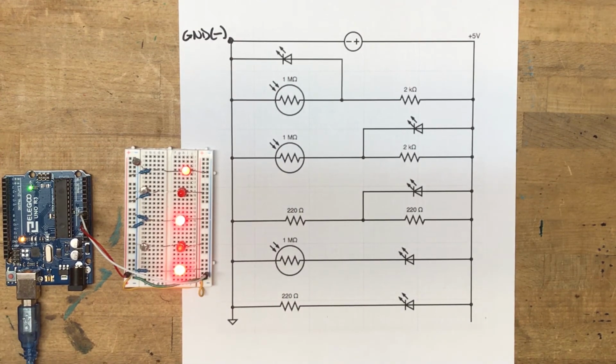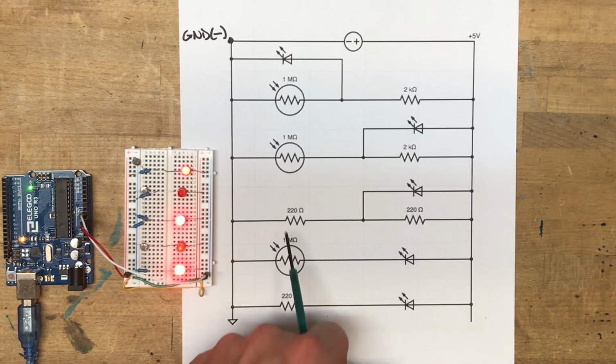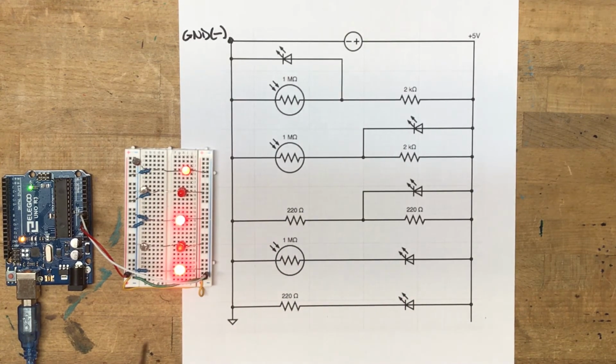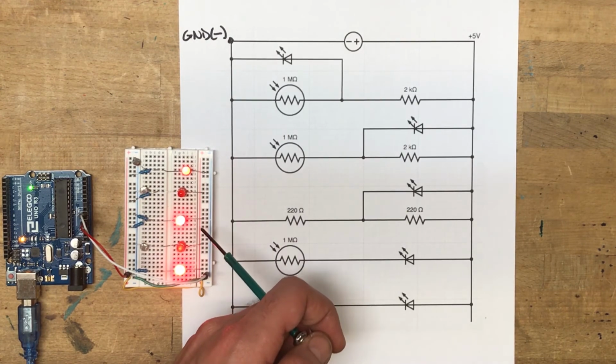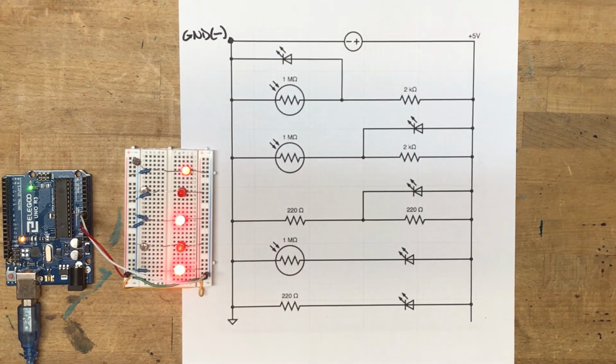Because we know in a voltage divider like that, we're dividing our voltage in half, and since we're working from the 5-volt supply, we know it's getting exactly 2.5 volts. So the red LEDs work perfectly at 2.5 volts. So if you really wanted to get right on, you can use a voltage divider. The next 2 above that, however, are slightly different.